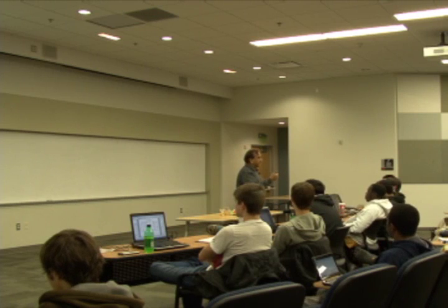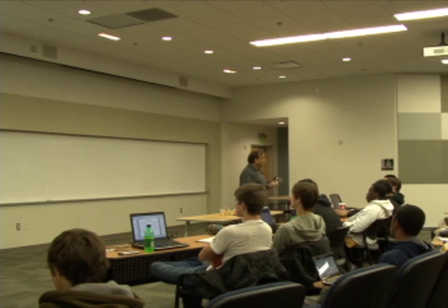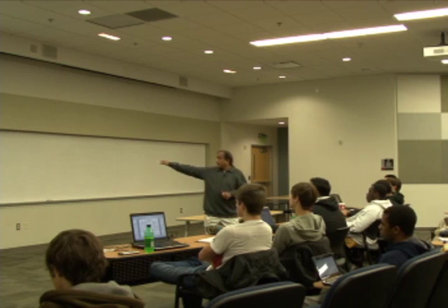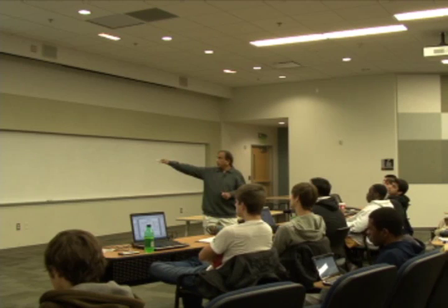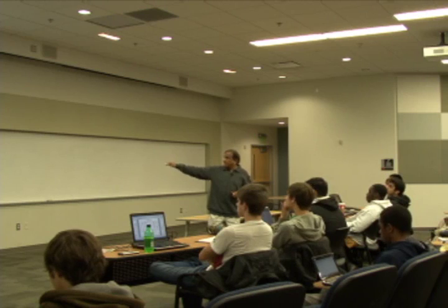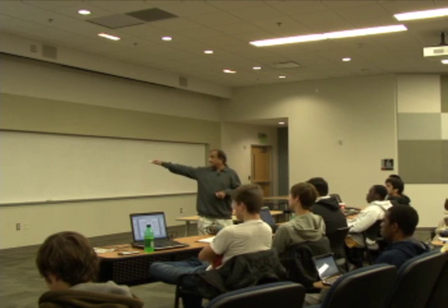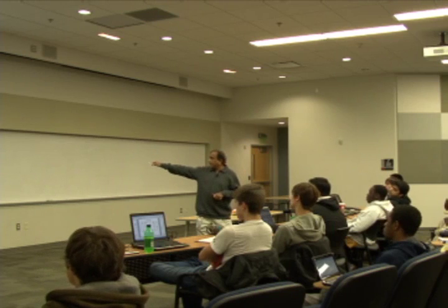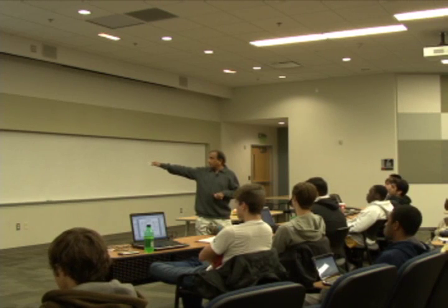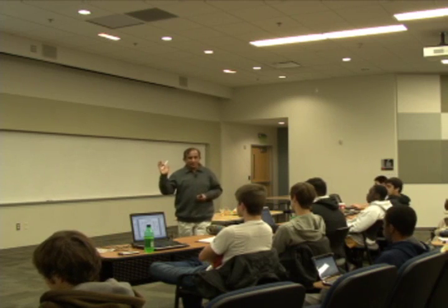So similarly, you can have a base address specified statically in the fetch microstate. The base address is go to execution sequence, okay? And the base address can be something like 1000, let's say. That's the base address. And we're going to modify the first 4 bits of the base address by the specific opcode that is coming from the instruction register, right? So if it's an add instruction, it's going to be all zeros. If it's an AND instruction, it's going to be 0001. So that's the prefix to the static address that is in the fetch microstate. Is that clear?